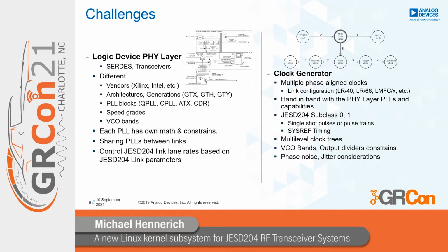Let's take a closer look at each individual component. The logic device PHY layer, basically the SerDes or transceivers. There are different vendors, just to mention a few big ones, Xilinx, Intel, Altera. Each of those vendors has different architectures and generations of their transceivers, GTX, GTH, GTY, for example, at Xilinx. Each of those transceivers has different PLL blocks, quad PLL, channel PLL, or Intel names them ATX and CDR.